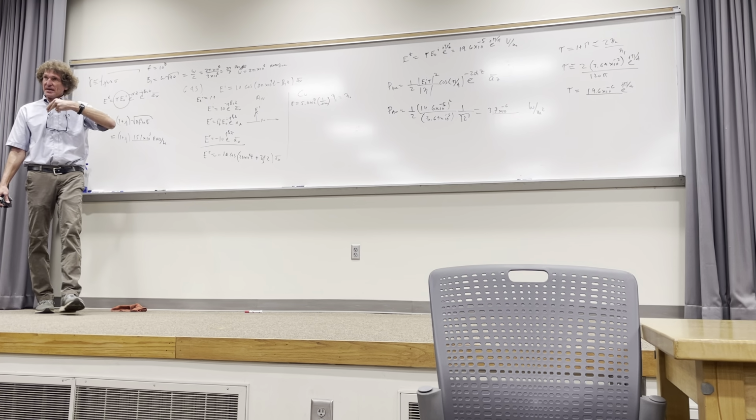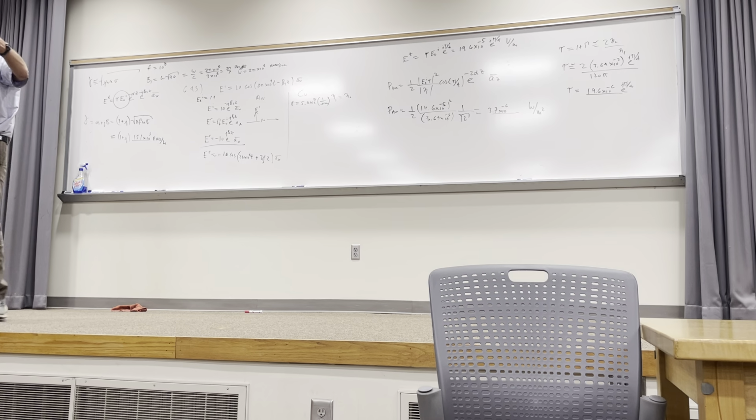So if you just take the incoming power density and multiply it by the square of the reflection coefficient, you get the reflected power density. Y'all hear me on that one, class? Something to keep in mind. Now, the truth is that's not quite true, because I approximated the reflection coefficient as -1, exactly, right? In truth, it's slightly less than this.